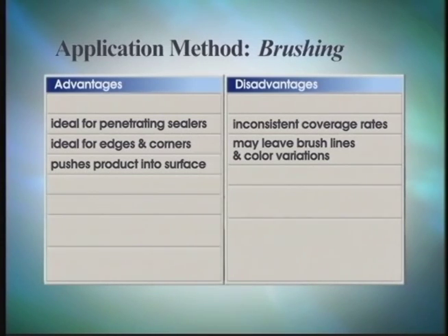Brushing. Advantages: Ideal for penetrating sealers. Ideal for edges and corners. Pushes product into the surface. Disadvantages: Inconsistent coverage rates. May leave brush lines and color variations.